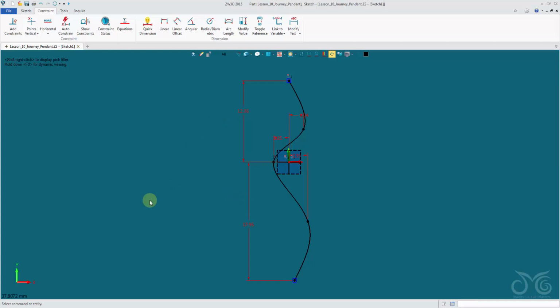Okay, so it'll be useful to make note of these current values approximately before we create our variables, because we'll need to create our variables with a value. So let's say the upper point offset is about 2, the middle about 2 also, the lower 3, top length let's say 12, bottom length 18. Remember we can't insert variables from within our sketch level.